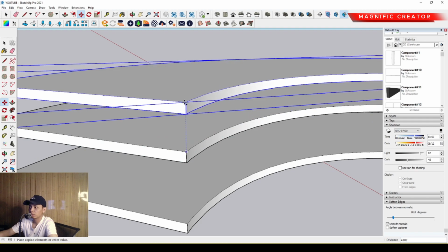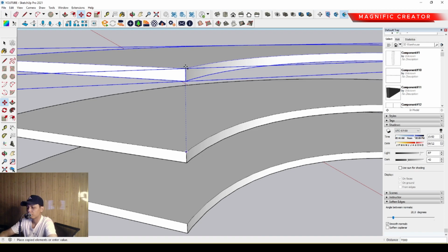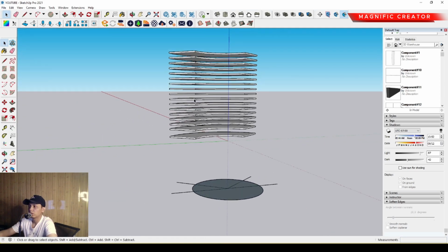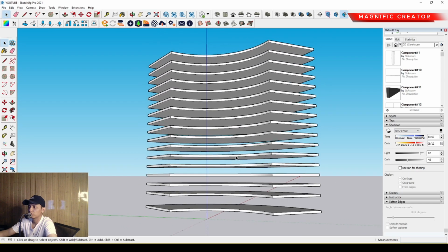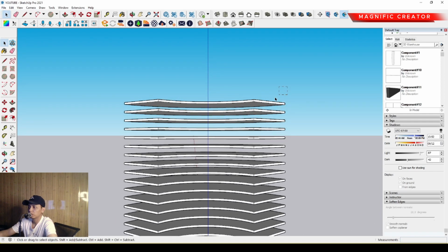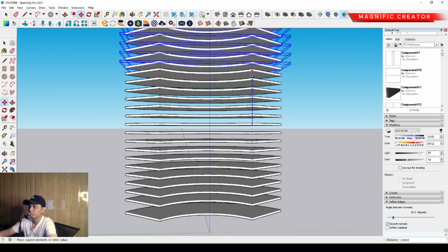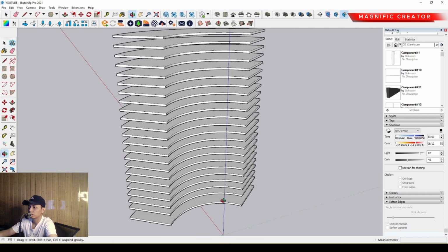We can set the floor to floor around 4.5 meter, and then we can duplicate it around x15. Okay, just like this, or maybe we can add more floors to the upper position to make it more high-rise. Okay, just like this, and it's done anyway.